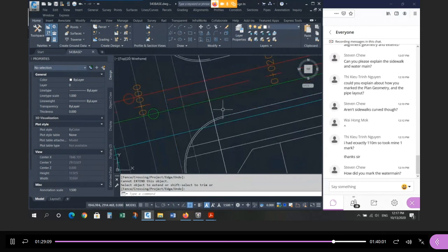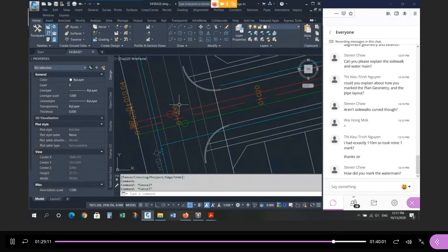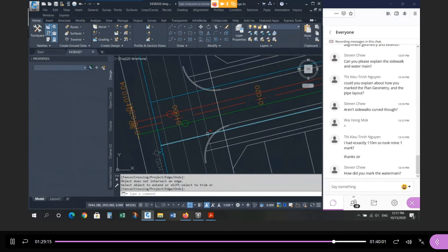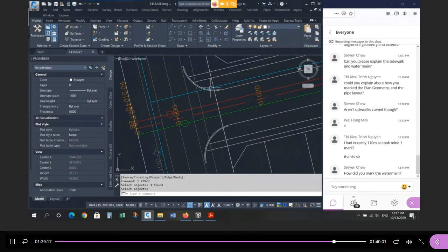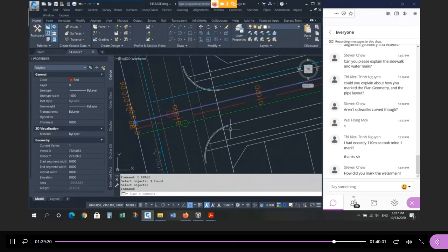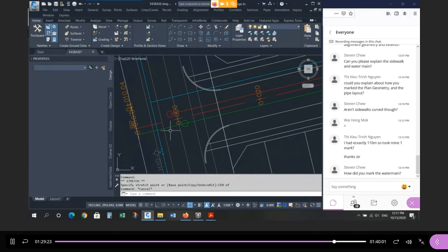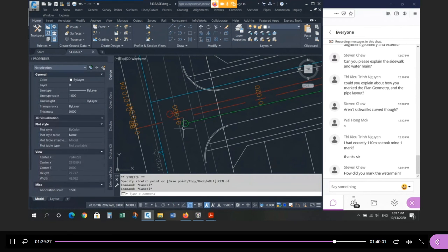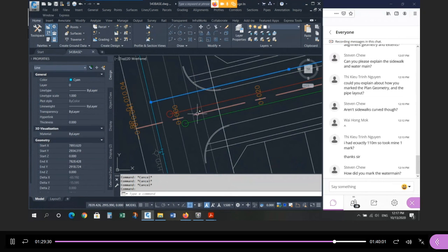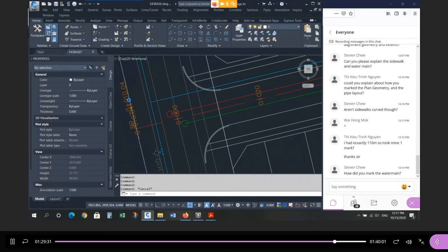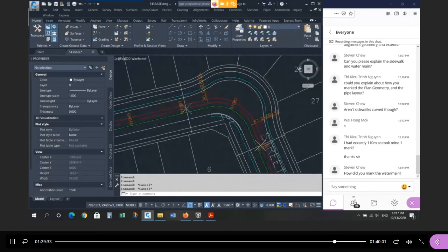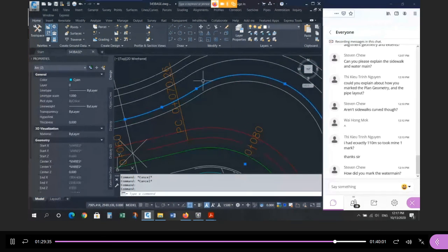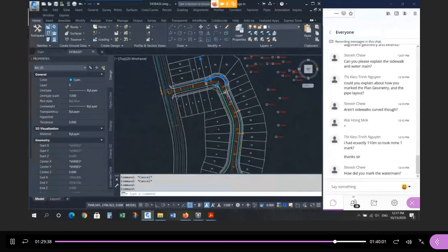That's your water main. Remember, it should be on this side. Extend to here. There are two options. This one's wrong. It's the one on the sanitary side of the street. These two would end here, and this would end here. The water main is on the same side of center as the sanitary, and you keep that all the way around. Just keep these curves. Don't do anything special here. Do it all the way here.